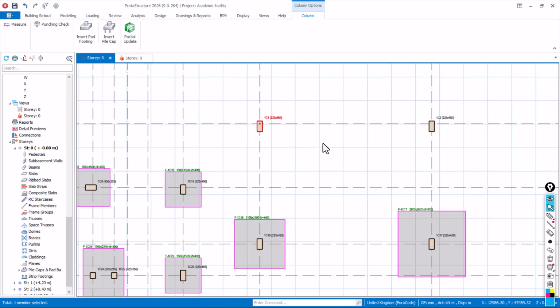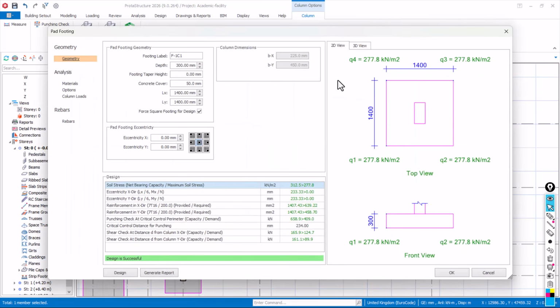Okay, now when it comes up, you can see this place that says footing eccentricity. We have several ways you can place your footing, either at an edge. You can see that when it was at this place, everything was passing based on the design, but once it comes to an edge, they are still failing. That is because there is now an overturning moment occurring at this place, at this side of the footing.